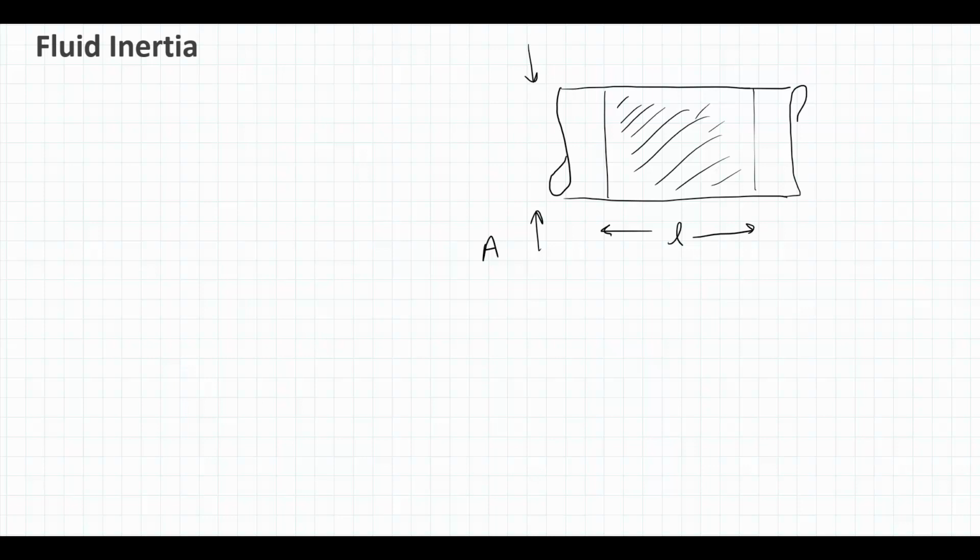So let me take out this little piece of fluid and see what is happening to it. Right, so our little piece of fluid is going to have some pressure acting on it on the left. I'll call it P sub L for left. And it's going to have some pressure acting on it from the right. I'll call P sub R. Now, these are pressures, so if I want to draw, let's say, a free body diagram, I am going to need to see on what cross-section these pressures are acting. So let me get this into a little bit more of a 3D shape.